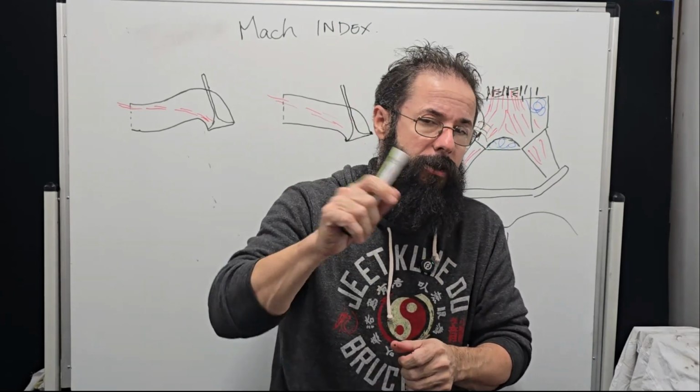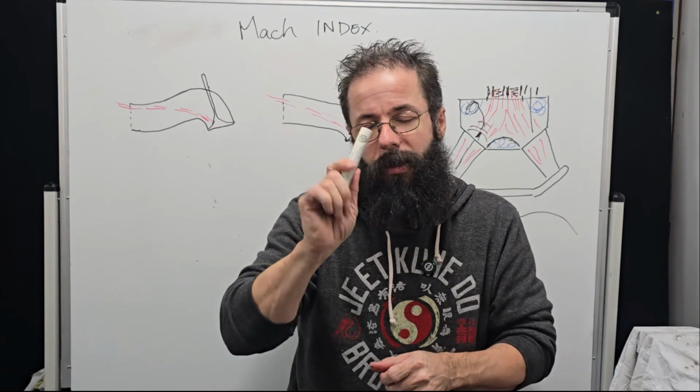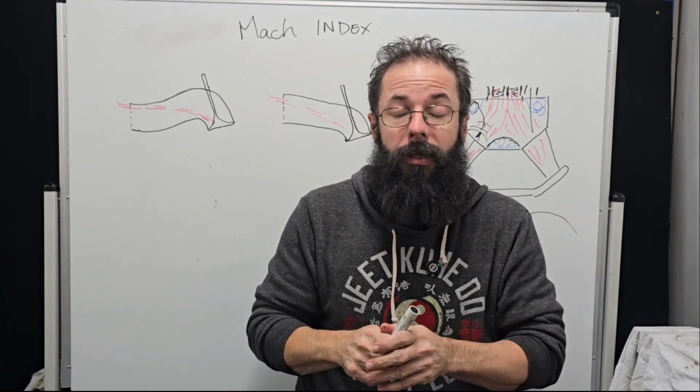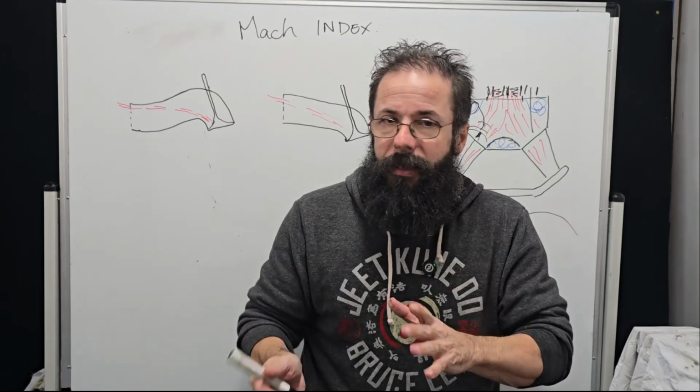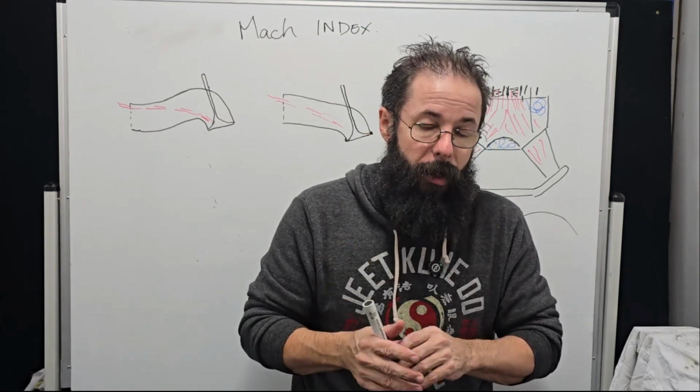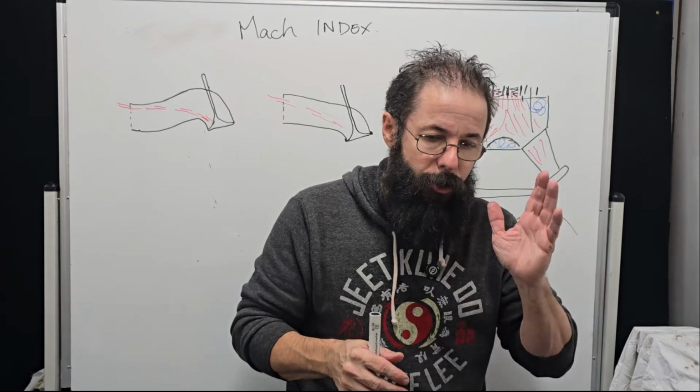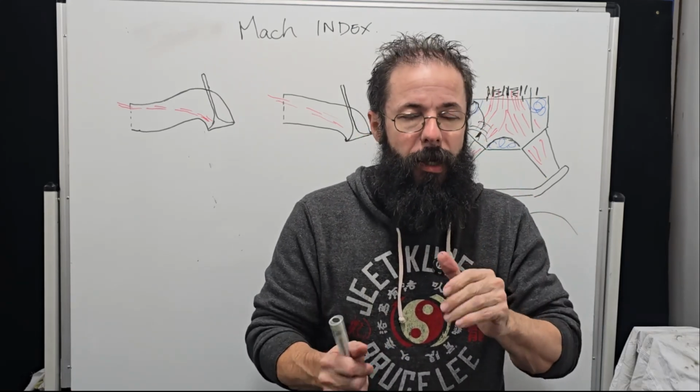And that's the, I think it's the rarefaction, I think that's what they call it, point in the wave cycle where they're basically not filling the cylinder properly. We've got a positive wave coming up, disturbs the airflow in the runner, and we get a power drop.